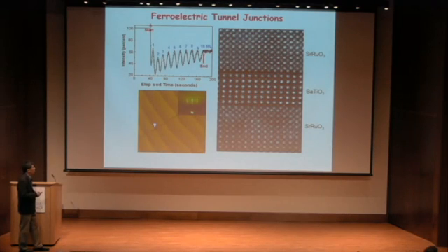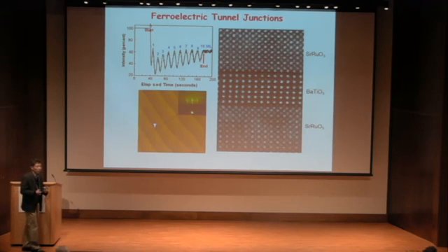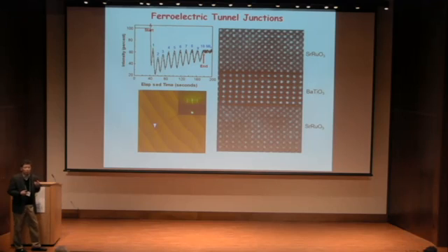For example, after growing these heterostructures, you can see the surface is almost the same as the single crystal substrate, and the interface is atomically sharp, and you can actually count the number of barium titanate layers. This is one example; I'm showing a different material, barium titanate, but the whole material is a stack without any creation of dislocations or defects. But we still have some point defects which cannot be observed here. It's very challenging to detect point defects in microscopy and other techniques.